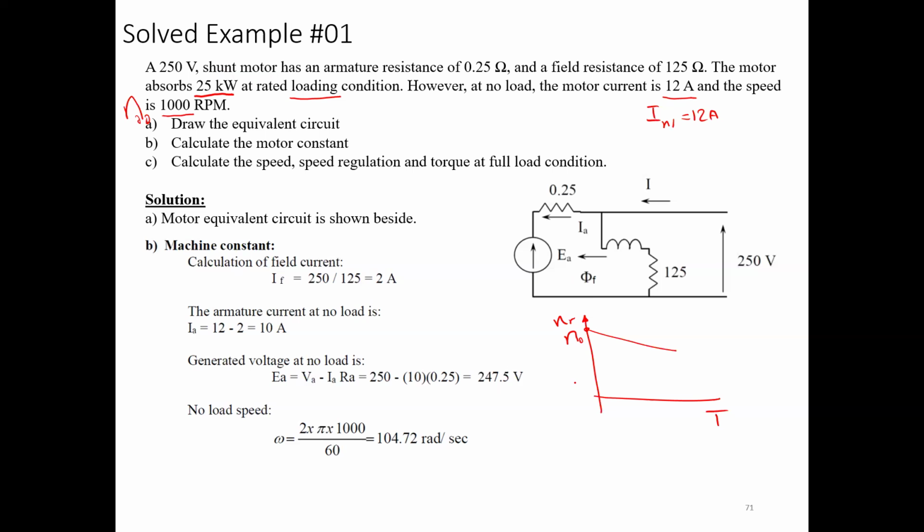What do we need here in this question? So first thing is draw the equivalent circuit. So drawing the equivalent circuit can be like that, guys. Just refer to having the armature winding in parallel with the field winding. It's not a condition to have the inductance in 90 degrees like that, but 90 degrees here with the inductance means you have the angle between field and armature circuit in terms of the configuration of the windings. Okay, it has to be 90 degrees.